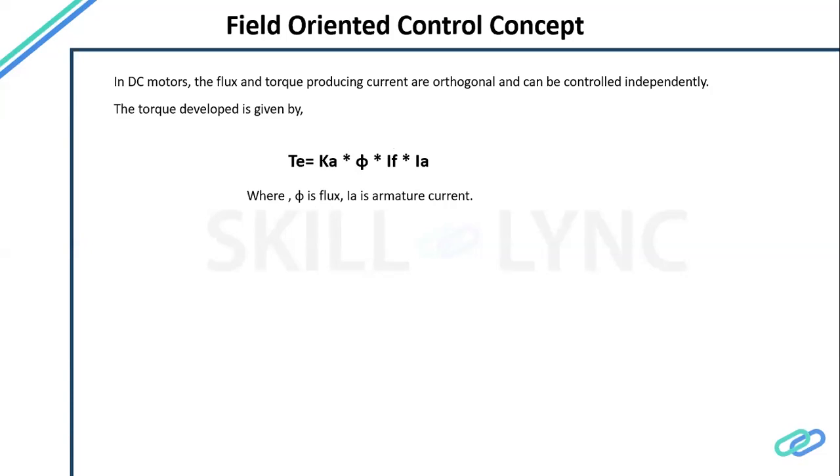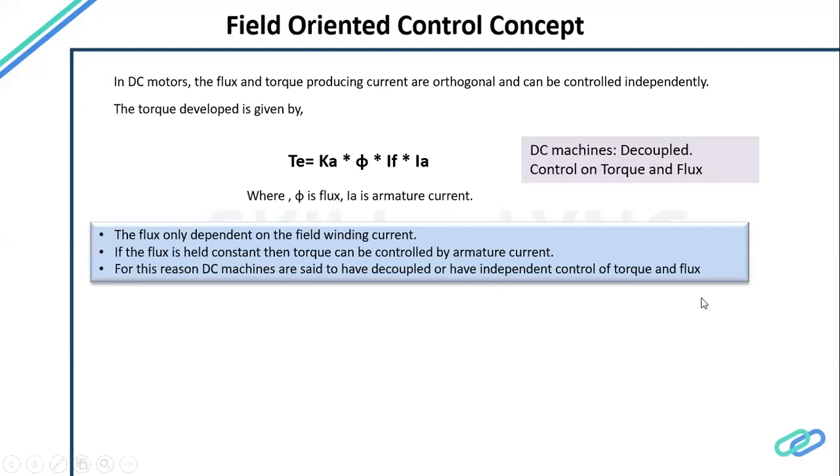So field oriented control, that is FOC, tries to make our AC machine behave like a DC machine from a control standpoint, so that we can control the direct axis current ID and the quadrature axis current IQ. This is the beauty, because at high speed we don't want much flux, because that creates a lot of back EMF, but we want torque. So it's a trade-off.